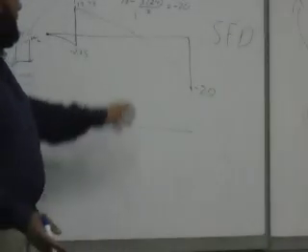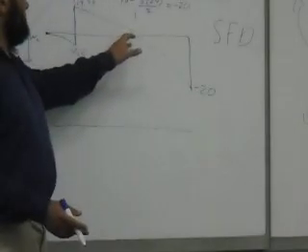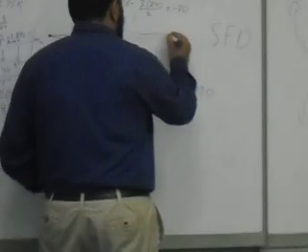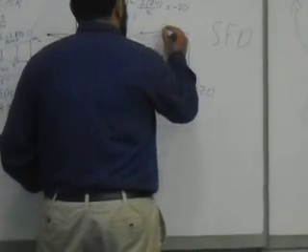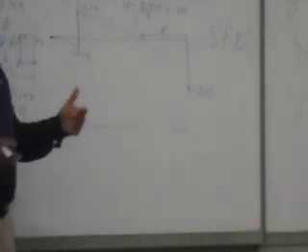The second important thing about the shear force diagram is the location of the zero shear, because this will tell me where the maximum bending is. So the location of zero shear here, approximately, because at the line it was positive here, maybe the zero shear will be at about 8 feet, more or less. And it's very hard to get it exactly, because this is not linear interpolation, this is not a straight line. This is something that you can get by trial and error.